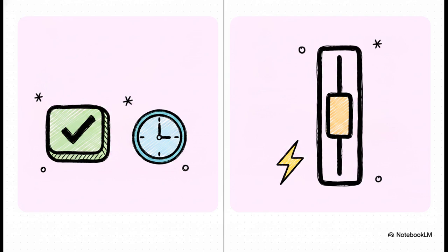Over on the left panel, labeled commitment, we're looking at generator on and off status across time. It is binary. Are you on or are you off? Then, jumping across the divider to the right panel, labeled dispatch, we're looking at the actual megawatt allocation among those specific units that are already online. Knowing exactly which side of this line you're operating on is step one for any grid scheduling task.